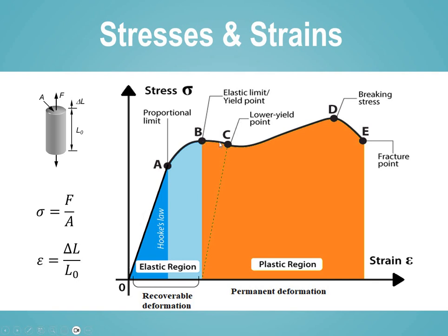After the point B, we are going to plastify the material, so the material will be behaving in a nonlinear way, but additionally, we are going to have permanent deformation. So for example, let's say we unload the structure at the point C. We are going to have an unloading path like this, and we are going to have these permanent deformations here, and some of the deformation will be recovered, so we will have some permanent deformation and some non-permanent deformation.